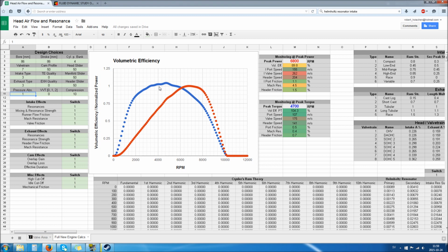But as you also can see, the volumetric efficiency doesn't change as it is supposed to, and that is deliberate, because I don't want to have a graph which just resizes all the time, but one which stays in the same place. So that is currently normalized to 1. The thing with turbocharged engines is that if you have 1 bar of boost, then you have a total of 2 bars, and that's the pressure absolute. So this one should be at volumetric efficiency of 2. Like, just take this times 2. But you see you are losing quite a bit in actual efficiency per boost, so to say.